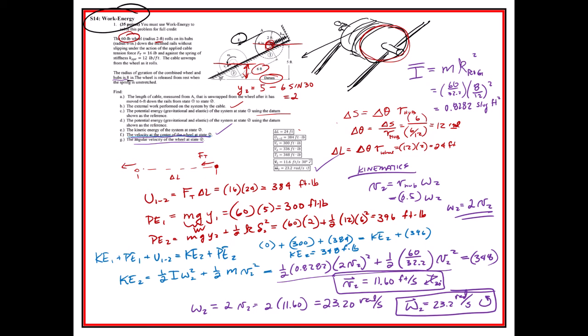Okay, how do we know the way the arrow goes? Well, I think the easiest way to do that, if you ever have a question, is to try the instantaneous center of rotation if you possibly can. So ICR is really helpful.